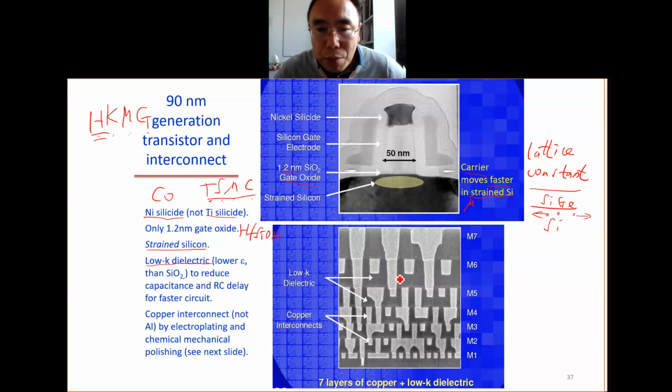Here, if we look at the material in the 1990s, as we talked about in the slide, it is SiO2. This material is not very good because of the RC delay. RC delay is big. So what is RC delay? Imagine, I draw it here. You have the metal here. This is like two terminals, like this gate, and this is the source of another device. So you have the metal wire.